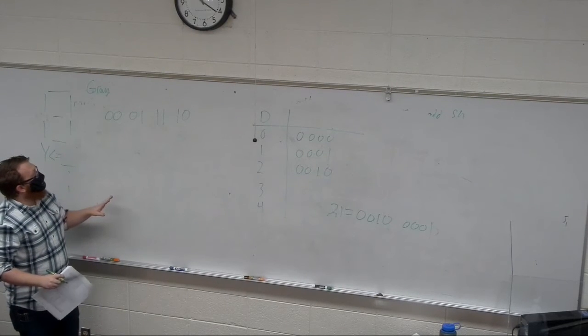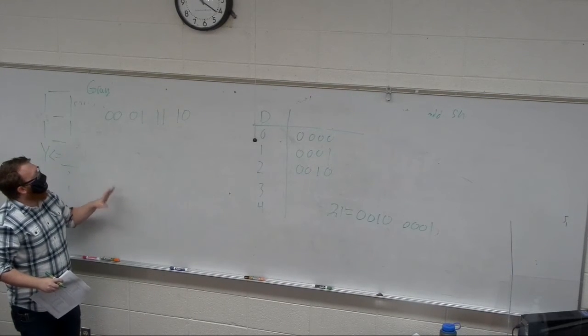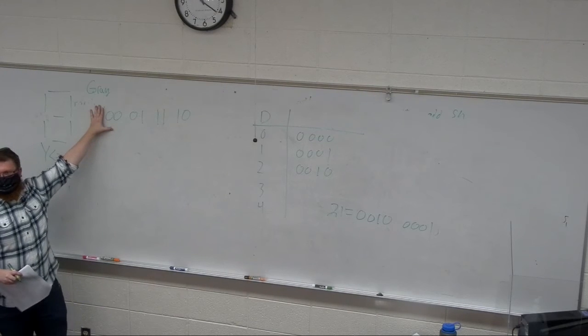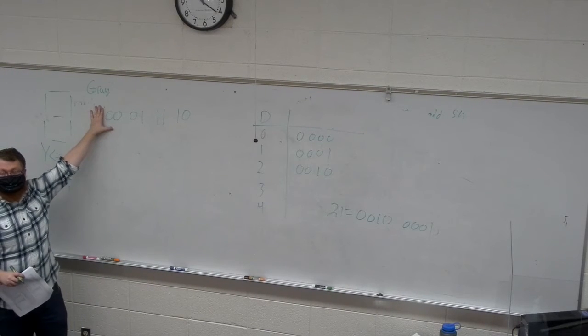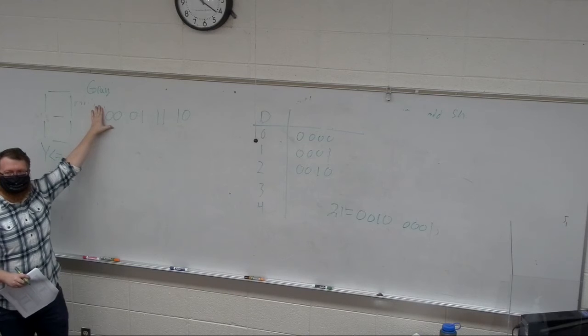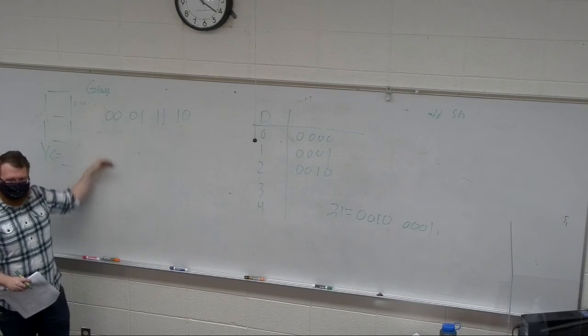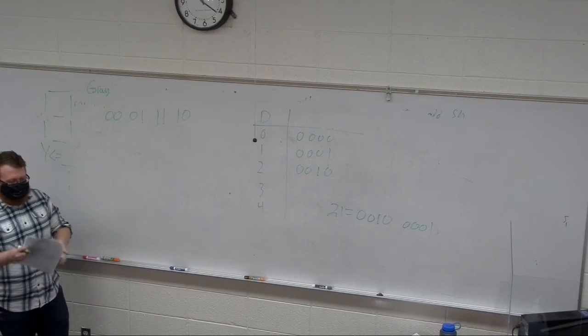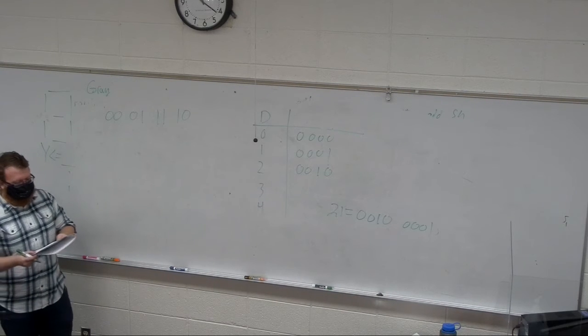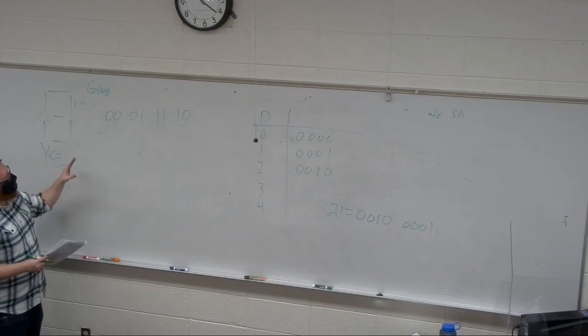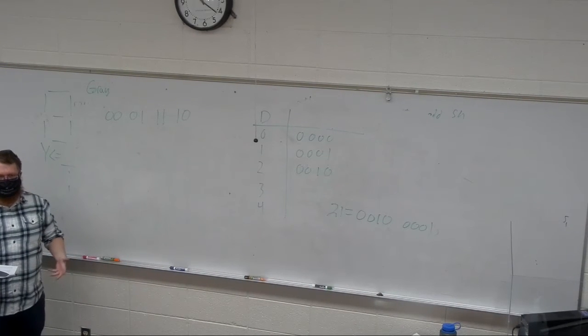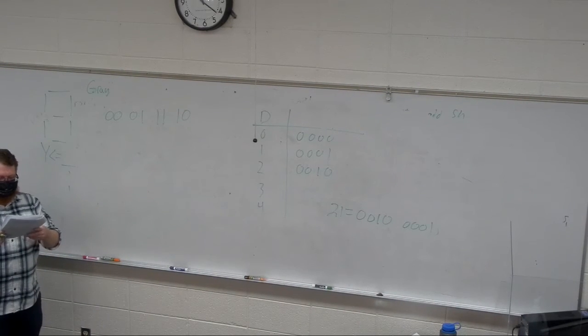We extend this all the way out to however many bits you have in your vector. I don't think I'll go into all the reasons we do this, but it's very optimal when doing counting operations. Because if I only have to change one bit at a time when I count through something, we consider that optimized and it's helpful. So yeah, that's gray code. You encountered it before. Now you have a name for it.